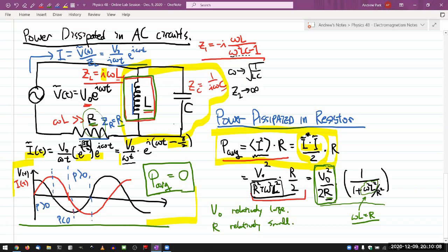In some sense, inductor and capacitor cancel each other out. And when you are installing a capacitor here for a particular purpose in mind, actually this frequency will be your operating frequency. Or rather, you pick your capacitance values so that this condition is true at your operating frequency, precisely with the intent of making G1 approach infinity, or make it infinity.